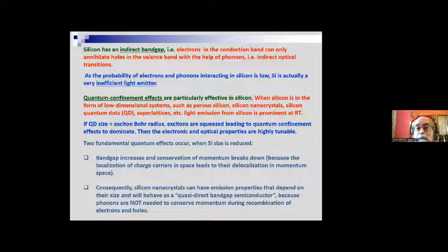And the material having the lower band gap has to be thinner compared to the silicon. And if you have multiple layers like this, a periodicity where the periodicity has to continue, in that case we are basically having a superlattice structure. And in the superlattice structure of silicon germanium, why it is important, I will tell you in a minute.